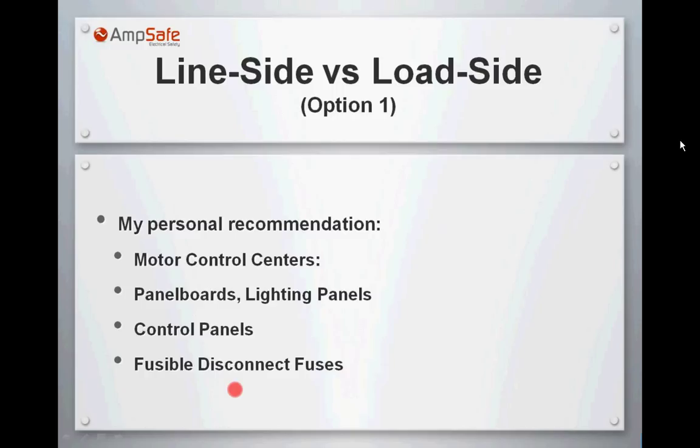I know this is kind of tricky with control panels because you have a small section where you have 480 volts. You have the incoming line side, you normally have a fuse or a breaker, and after that fuse or breaker, you probably have a step-down transformer that feeds all this electronics in this section of the control panel.